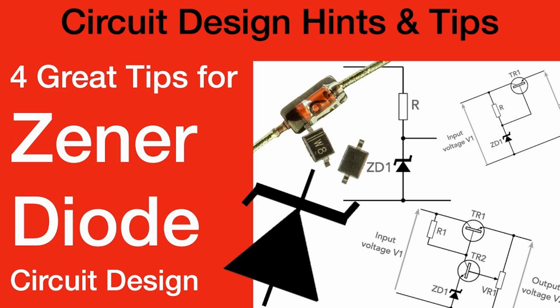2. Overvoltage protection circuit. An overvoltage protection circuit safeguards sensitive components from voltage spikes. Components: Zener diode, VZ. Load device, e.g., microcontroller. Design steps. Choose the Zener diode. Select a Zener diode with VZ equal to the maximum safe voltage for the load device. Example: for a microcontroller with a maximum voltage of 5V, choose VZ equal to 5V. Connect the Zener diode in parallel with the load device. When the input voltage exceeds 5V, the Zener diode conducts and clamps the voltage to 5V, protecting the load device.